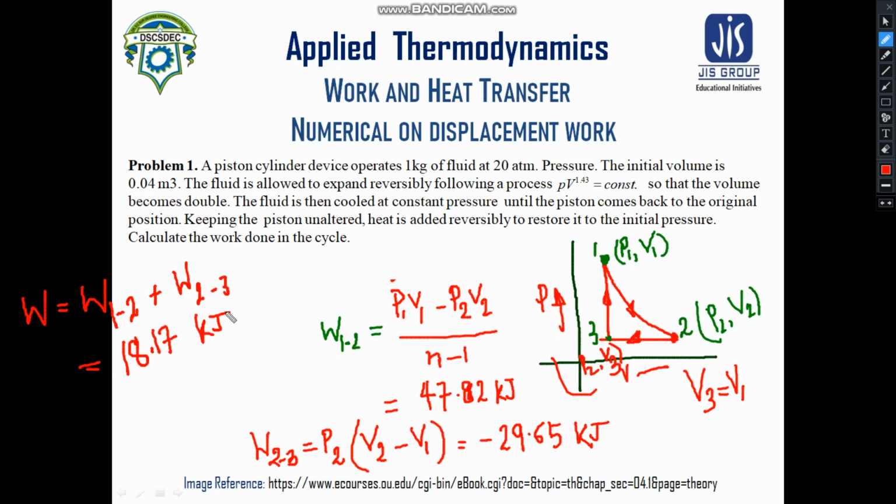You just need to understand the nature of the thermodynamic process, and you will find a certain thermodynamic relationship is always given to this certain process. A pressure volume relationship is given to you, and whenever you know that pressure volume relationship, you can put it into the PdV equation, and then you can get the desired data.